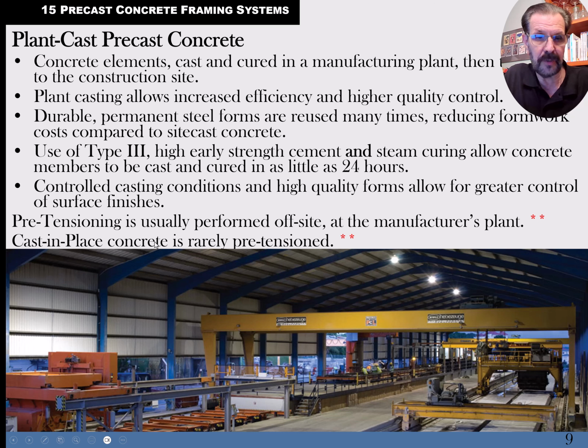Cast in place, on-site concrete is rarely pretensioned because you'd have to have the form to do it, but you can certainly do post-tensioning on any site. So post-tensioning is something you're going to see more of in your experience.